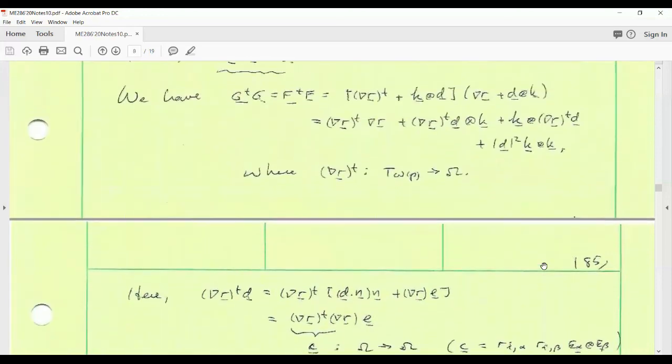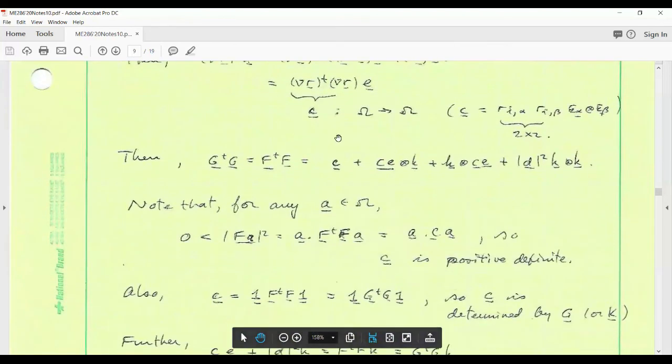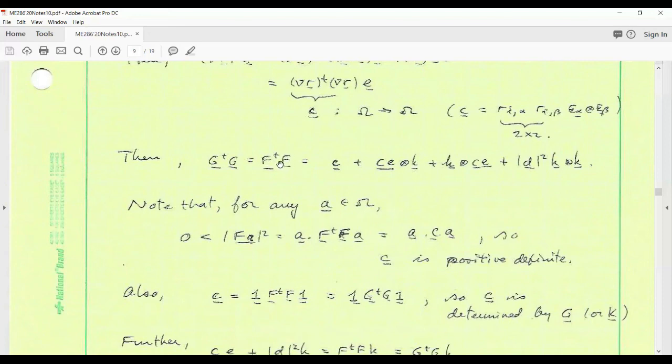And with that definition of C and this result, you go through here and you get the 3-dimensional Cauchy-Green deformation evaluated in the midplane is this 2 by 2 part, C, E, tensor product K. These are like transverse shear terms. This is in the initial plane.